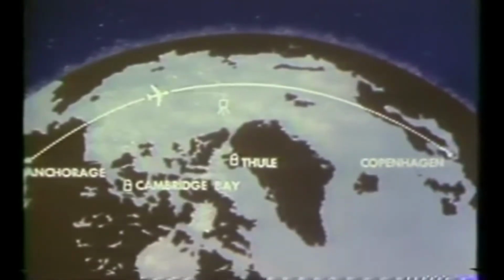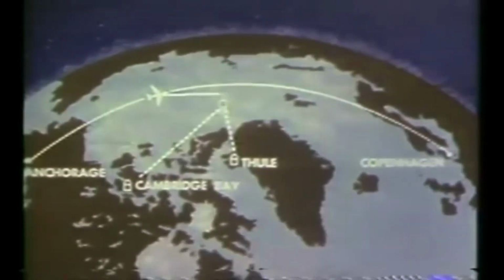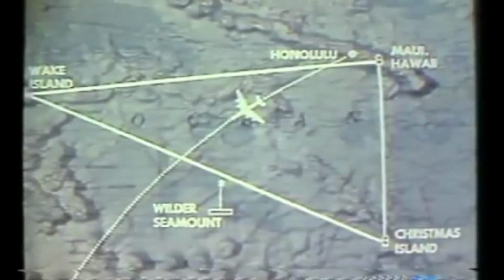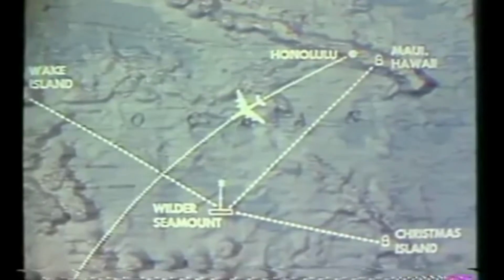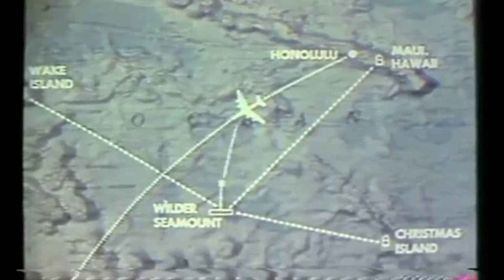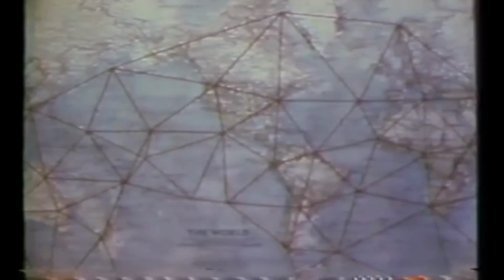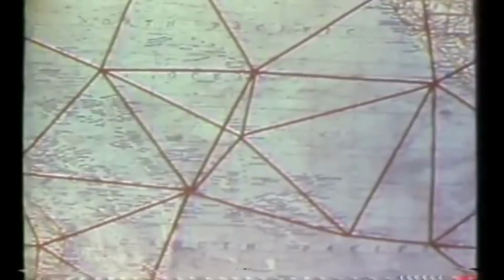The accuracy and position determination attainable for these various types of beacons, whose location may also be constantly shifting, is dependent upon the availability of adequate position-fixing ties between these beacons and their reference, or base stations, as well as a high degree of positional accuracy in the base stations to which they are referred.